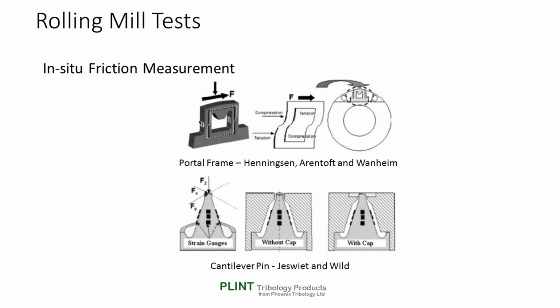Over the years, a range of devices have been developed to allow measurement of local friction forces within the roll bite, with the aim of overcoming the limitations of some externally sensed total force systems. These have been used in both laboratory and full-scale mill rolls. Although in recent years the trend has been to use mathematical models of metal forming processes, verification of frictional behavior with experimental data is still required. These types of sensor offer the best option for providing such process-based data.